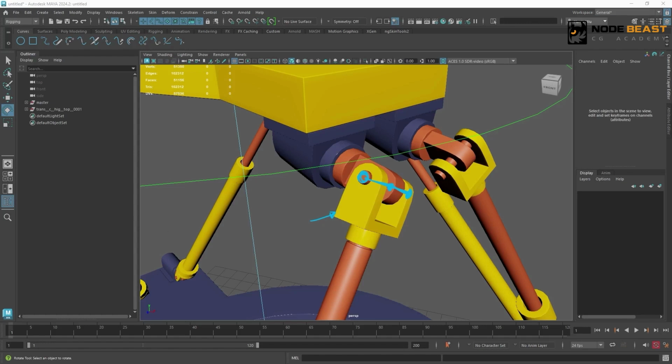Next, where is our up reference object's point? Let's draw this out together. We know our aim constraint's driver point is the lower part's rotation center, so the aim vector must point down in this direction. Then we know there's a rotation hinge here, so one axis must be pointing along it, and the last axis will be pointing forward.